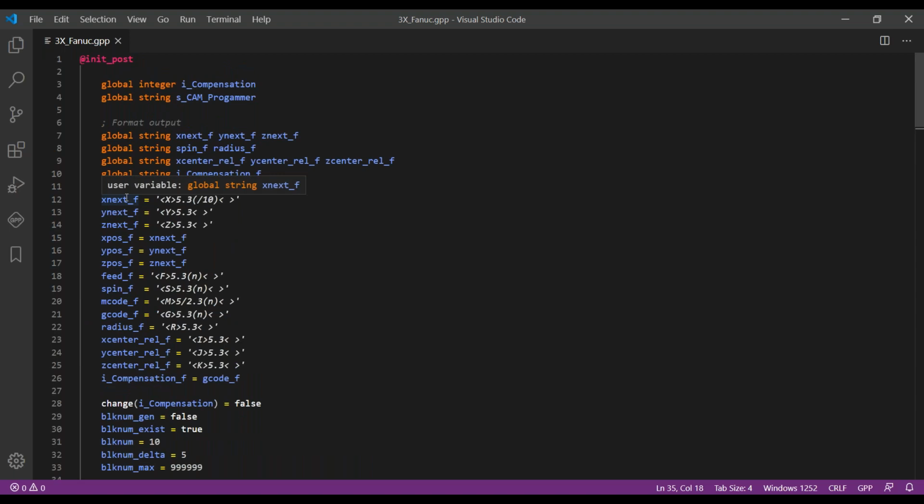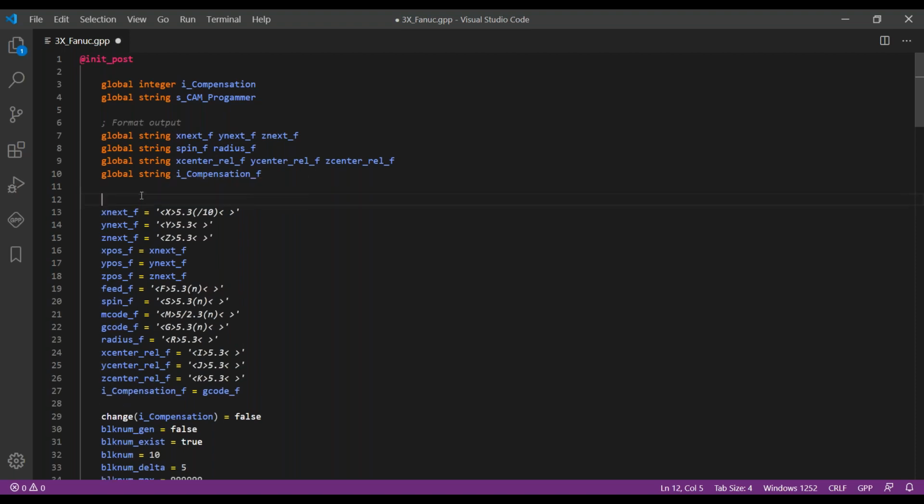If you try to declare, for example, I don't know, apos_f, SolidCam will give you an error that it's not possible. Can you, Kashin, for now, just write apos_f? As you can see, this is a system variable. This is coming from the system, and it was from the past.